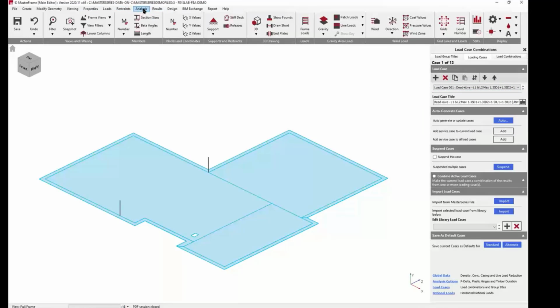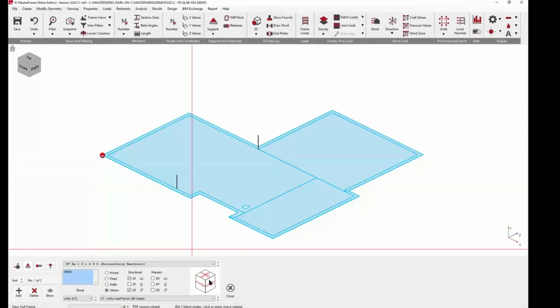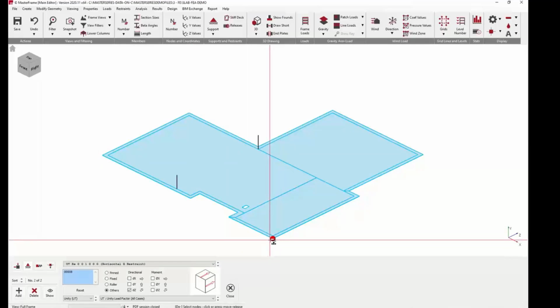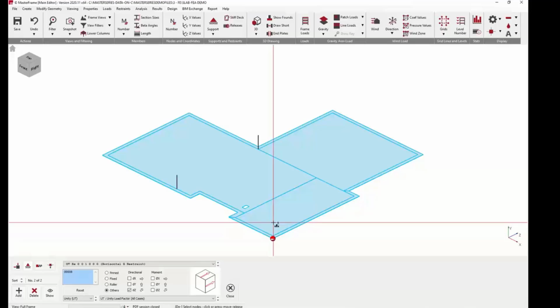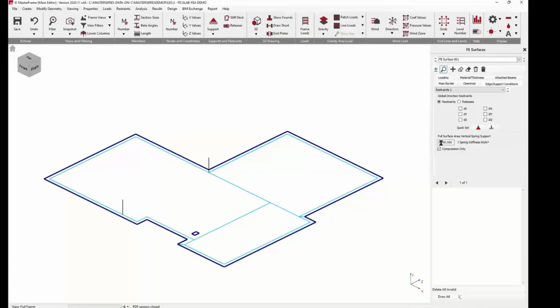But before we do that, supports, the most important thing. And let's look at our restraints, static supports. I've got a support here that is a pin, but with no vertical. And I've got another one over here that's a horizontal, no vertical. And those 2 supports together stop me having a couple spinning on plan. It gives it X and Z directional stability. What the other thing we've done is we've put in a spring stiffness.